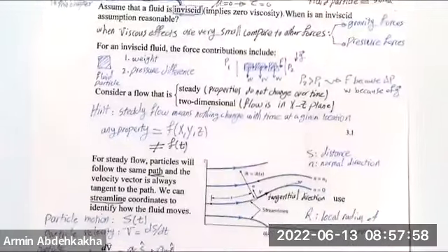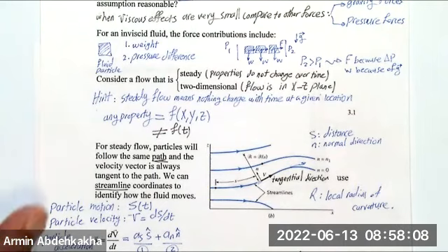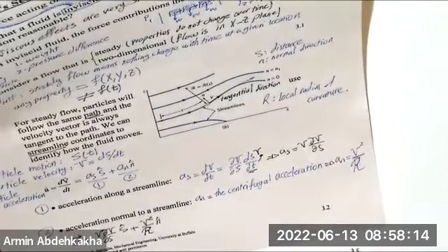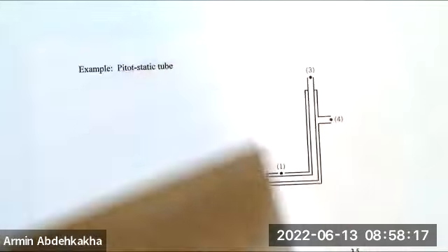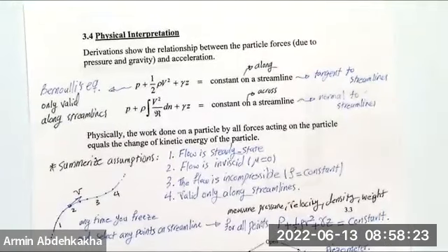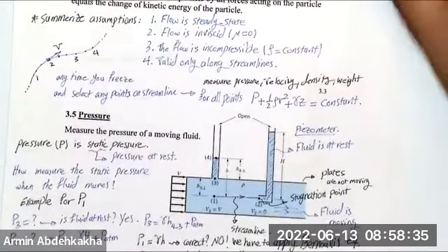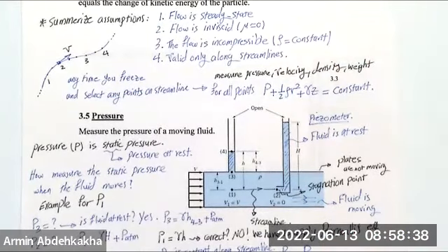We talked about the acceleration of a fluid particle, and how we can calculate and measure the acceleration and velocity. Then we also talked about the pressure and Bernoulli's equation, how it's constant along a streamline, and how we can calculate the pressure when the fluid has a velocity and the pressure is not always the same as for the fluid at rest, which is the static pressure.